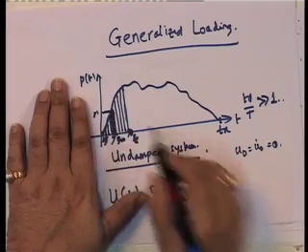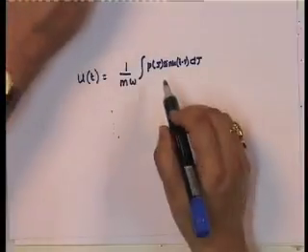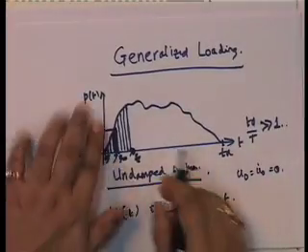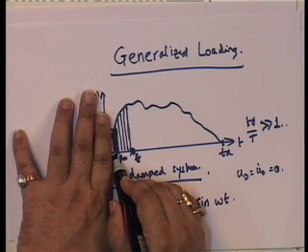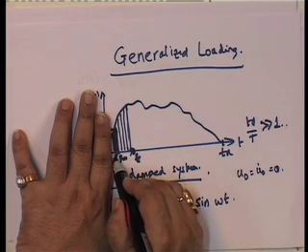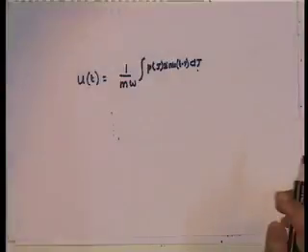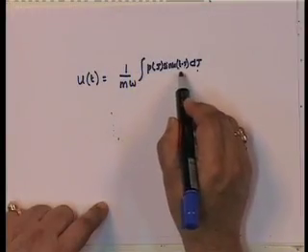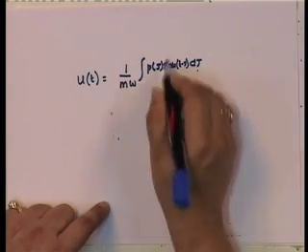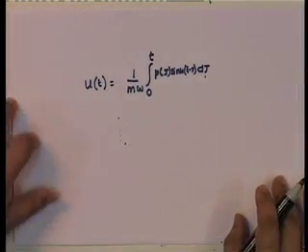The impulse becomes p tau d tau, and the response is going to be sine omega t minus tau, because the impulse was only given at time tau. So, t minus tau is a shifted time. This is the response, and therefore, if I consider all the trains, all I need to do is integrate from 0 to t.